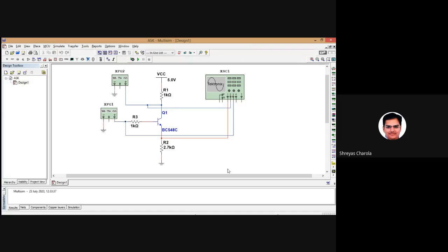Okay. Now, if I want to use a transistor as a switch, should the input at the base be digital or analog? Digital. If you are using a switch, it has two values: either you switch it on or off. If your transistor is on, then and only then the current from the collector will go to the emitter and complete the path from VCC to ground. If the transistor is in the off state, no current from VCC can go to the ground because the path is incomplete. It's an open circuit.